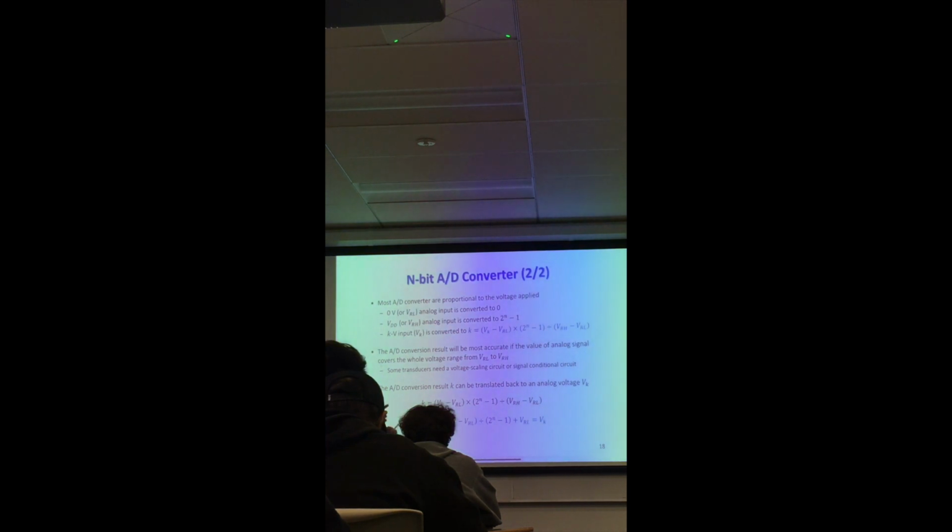You see, you always have to play with that. If you're guaranteed that you are interested only in this set of voltages and you want high resolution, you don't have to use a higher precision analog to digital converter. Okay, so you have to change the range of voltage that you are resolving.